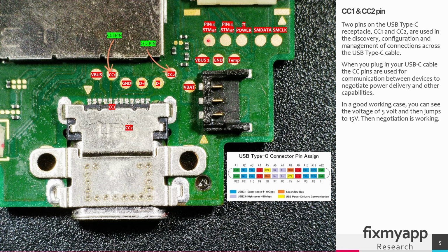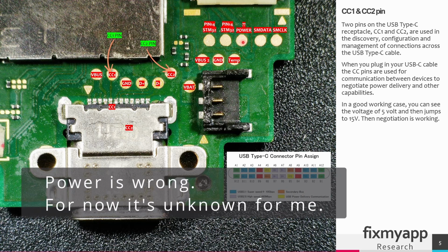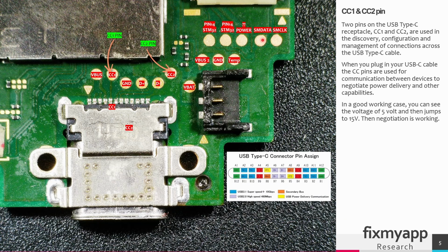These two test pads are going to a coprocessor. What it exactly does, I don't know, but it goes to the STM32 IC. This goes to the power button. That is the serial data line. So this is the clock signal and this is the data signal. Keep in mind that I reverse engineered these test points, so the meaning of the test point can be different, but I have a good feeling that it's almost correct.